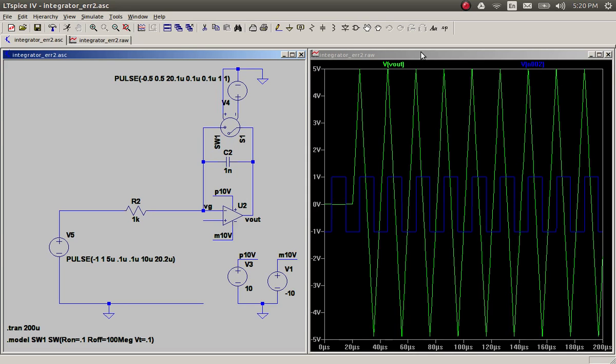So one thing to note is just because you get the output waveforms doesn't necessarily mean that your circuit is kosher. I mean, it's fine. It means that you may still need to look at the circuit and some issue might show up later. Because if there's a very large resistor and there's something injecting current into it in a real model of an op-amp, then you might have a problem.